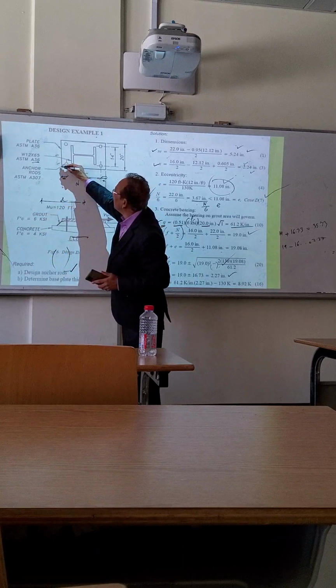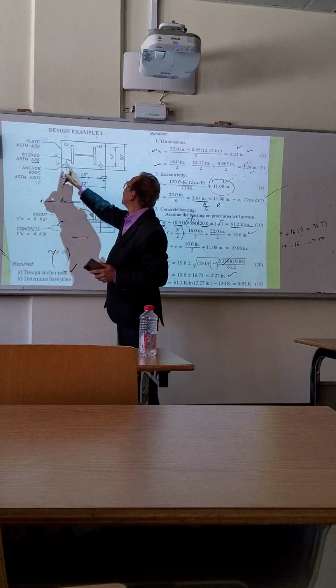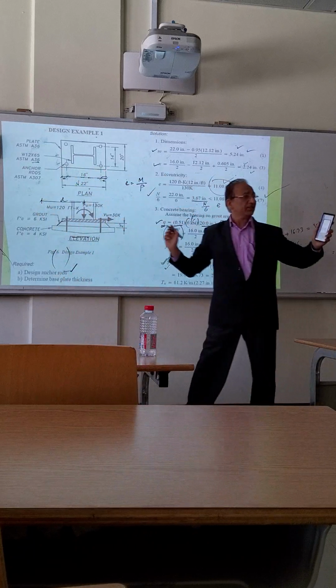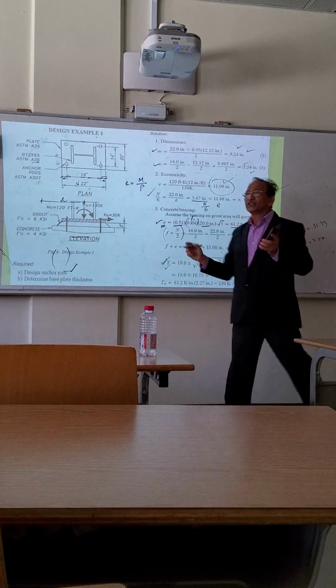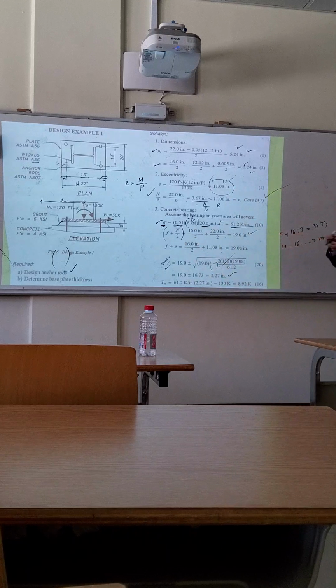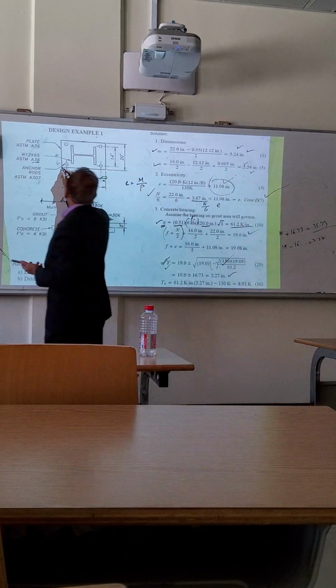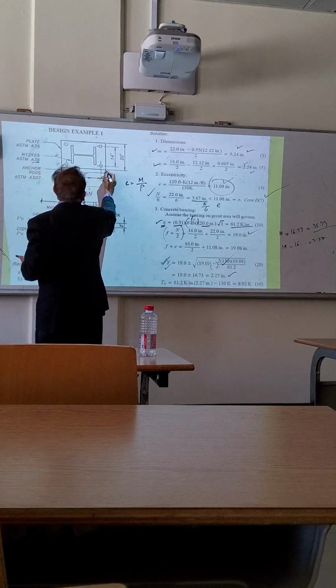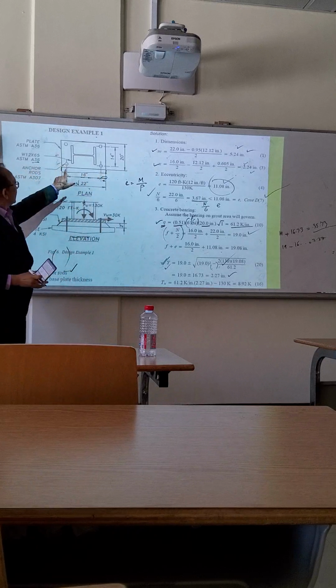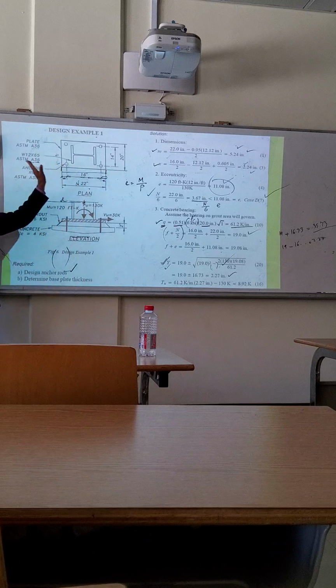This is your plate. The plate has only the length of 22. So there is no question of concrete and steel having a coverage of 35. Maximum it can be 22, right? Because concrete will be under the plate here. It can be less than this 22 or maximum 22.